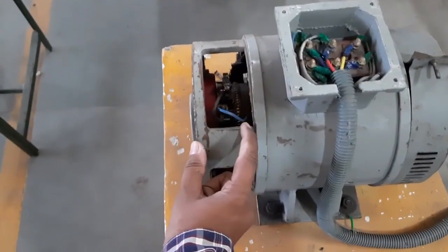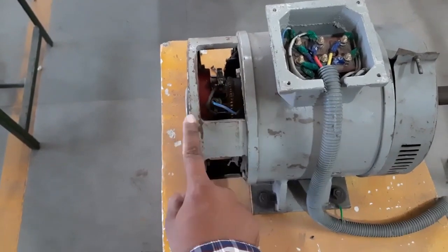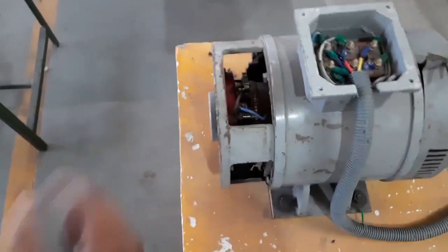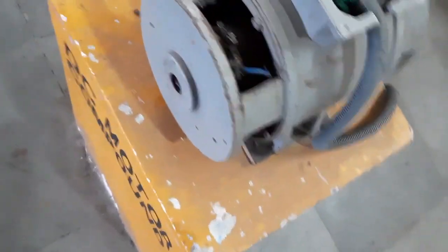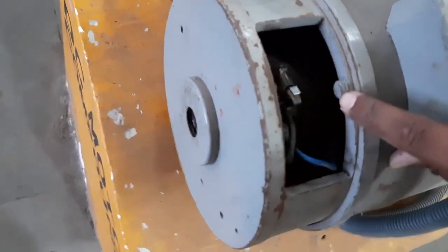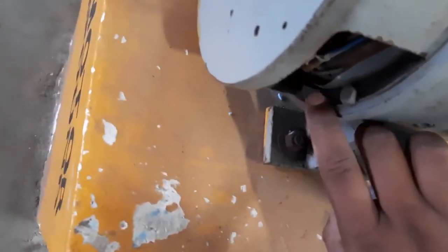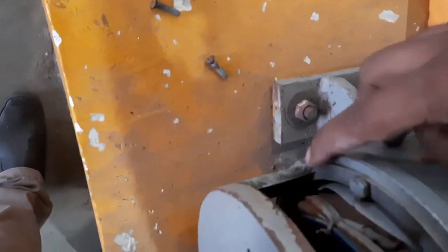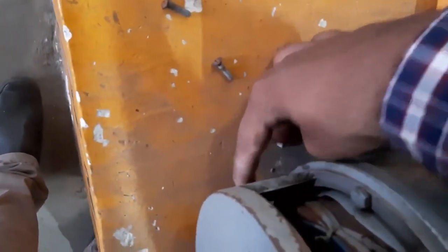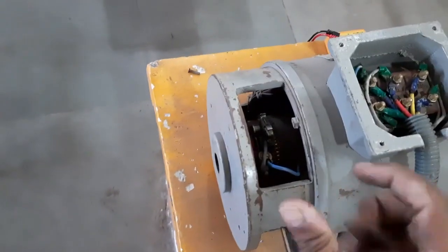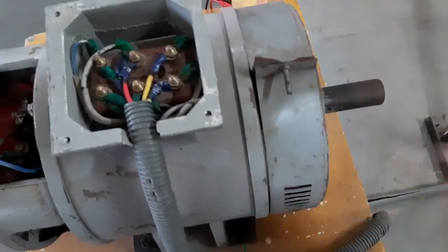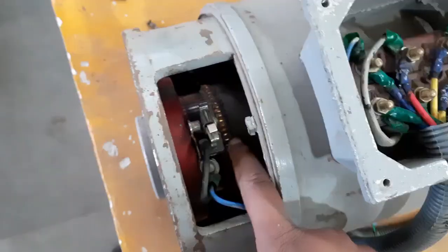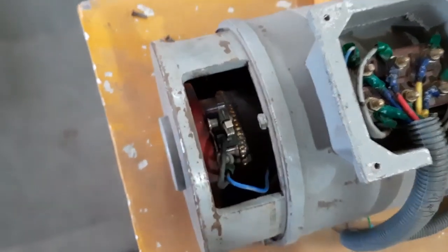Now if you want to open this particular generator totally, then you have to open this part. You have to open this part. This will be opened like this, and also this part will be opened in the other direction. But the question arises, how will we open this part? You can see there is a bolt connected here and here also, then the same in here also, and on the underside also. If you open all these bolts, then this part will come out of the generator, and we have to open this part also on the opposite side. When you do this, this armature will come out of the generator with these two parts.